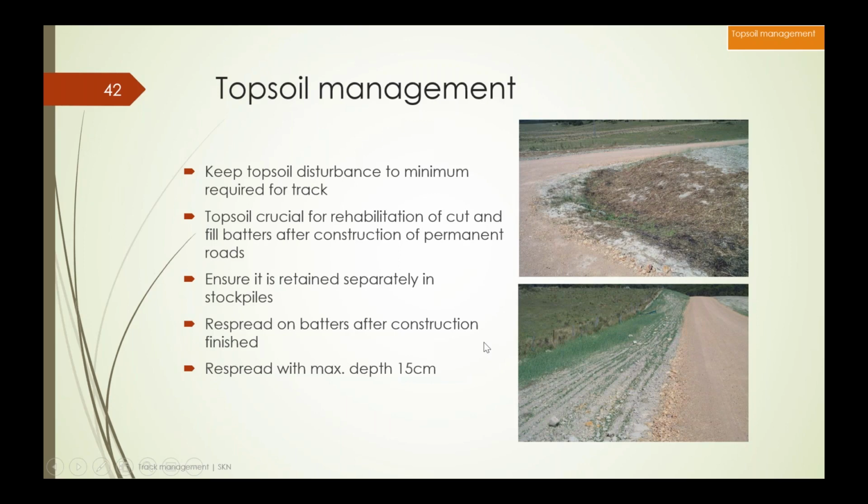And then when you can access it when you're finished, to respread on the batters. We recommend a maximum topsoil depth of 15 centimetres. Once we start getting deeper than that, we start to risk it slumping off the batter.